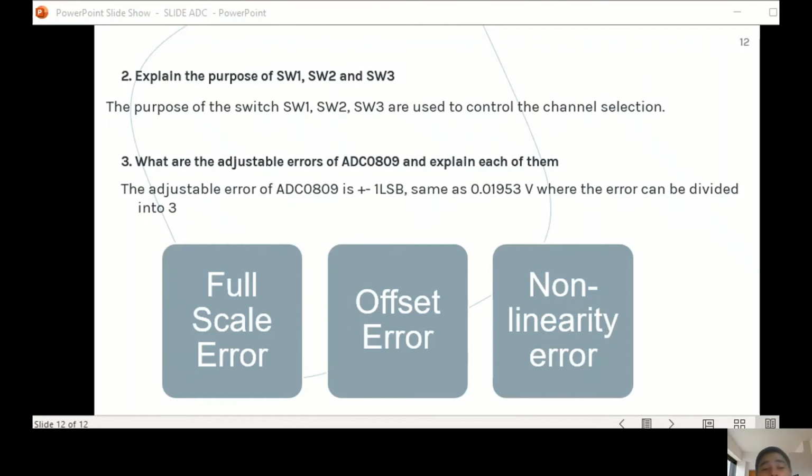The difference between the center of the least significant code and the same code on an ideal ADC with the same number of bits is known as offset error. The least significant bit, LSB, of the converter is used to detect offset error. The quantization interval of the converter is 1 LSB.